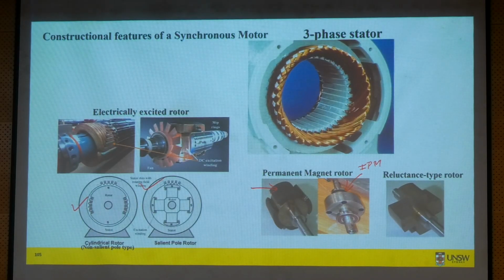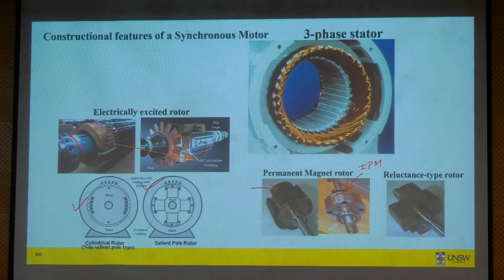So if I look at my D-axis flux, the D-axis flux will cross like this. The D-axis crosses the magnet. And remember, the magnet's permeability is the same as air, right? So it is crossing the magnet and the air gap, so it sees a higher reluctance. That's why the LD inductance is smaller for the IPM machine, and it behaves like a salient pole machine.